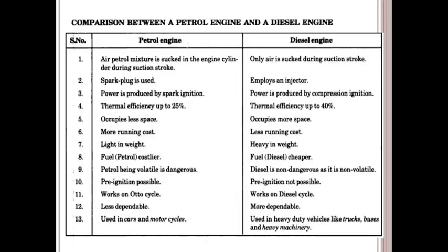So another comparison, guys: petrol engines and diesel engines. In a petrol engine, an air-petrol mixture is sucked into the engine cylinder during the suction stroke. In a diesel engine, only air is sucked during the suction stroke. In a petrol engine, a spark plug is used. Here injectors are employed. Power is produced by spark ignition. Power is produced by compression ignition.